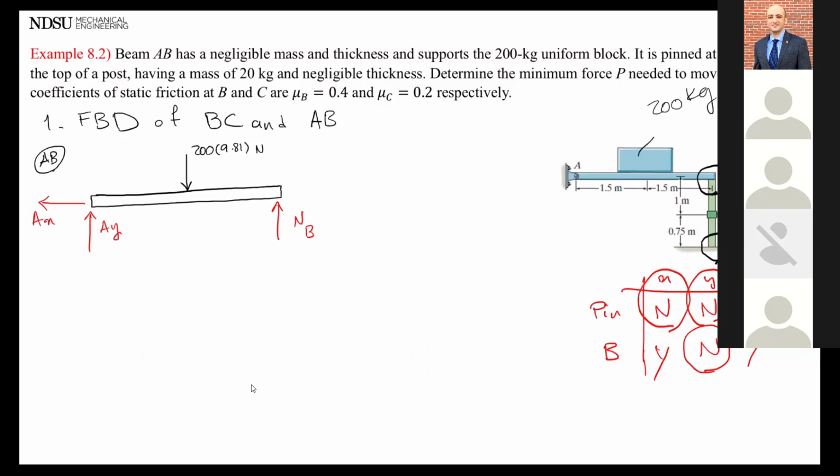Okay, so what else do I need at point B? What is this chapter dealing with? A friction reaction. Friction, okay. Friction is perpendicular to that normal force, or tangent to the surface, right? This is the surface of contact right here. So friction is tangent. So friction is going this way. Let's put it in blue color.